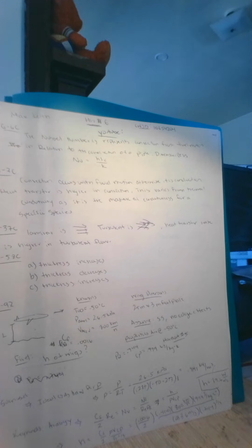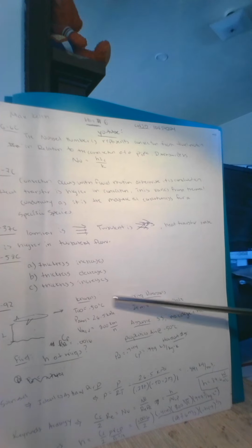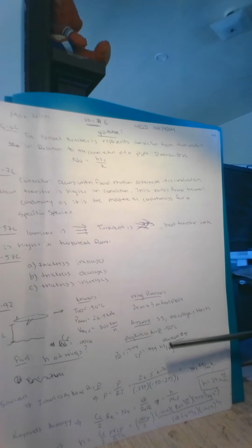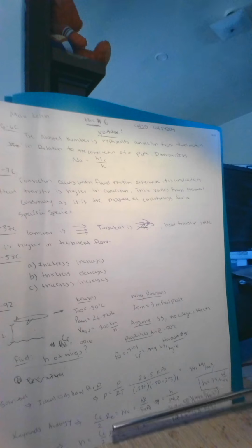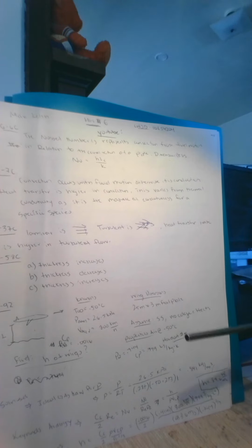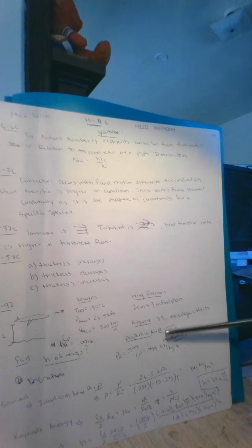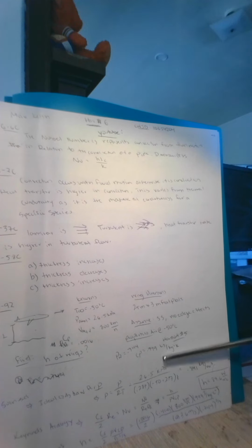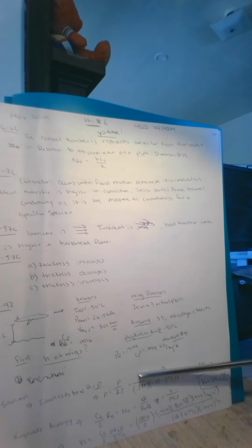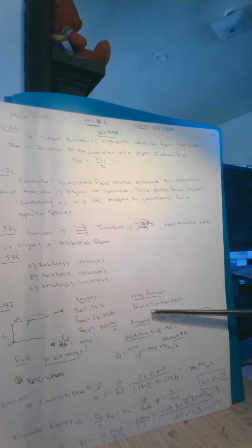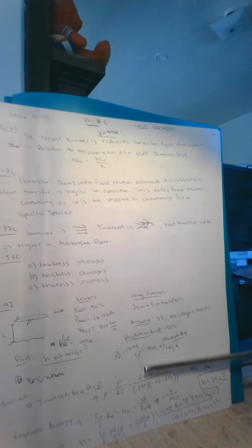Okay, so for homework number 6, Tracy Gardner's heat and mass class, for the first question we were asked to find the heat transfer coefficient for a plane flying at some altitude with some surrounding specifications. And first thing we did was go to handout number 5, get the properties for the air that the plane was flying through, and then we applied the ideal gas law to get a density for the given pressure that we're at.